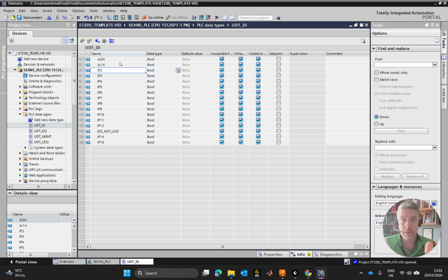So if you look at a cylinder on that plate, the extension is usually to the right of the retraction. If the cylinder starts retracted, in its normal state, the left-hand side device, whether it be a roller switch or a cylinder-mounted mag, is typically mounted to the left. That's the zero limit, the retracted limit sensor or switch. That's left, so that comes first.